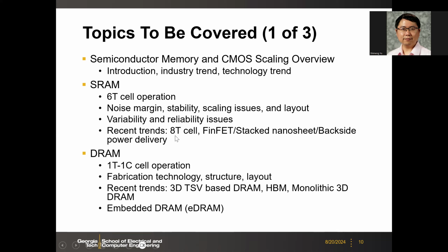So here are some things that I added for this semester. Because 3 years ago, I only thought about FinFET-based design. But you know, the industry is evolving very fast in this space. So I'd like to introduce new topics for the leading edge node. That means 3 nanometer, 2 nanometer, 1 nanometer, and beyond. Including the transistors based on stacked nanosheet and backside power delivery, which is important to maintain the scalability of the SRAM for the future technology nodes.